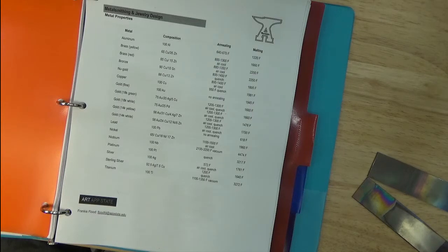So by annealing the metal, which typically involves heating the metal to its annealing point, we're able to spread that crystalline structure back out, and then we can bend the sheet and work harden it to a certain point where it gets stiff or rigid. Then we can heat and anneal again, and do more forming to the piece, and it would work harden, and then we could anneal again, and you can keep repeating that cycle over and over and over.